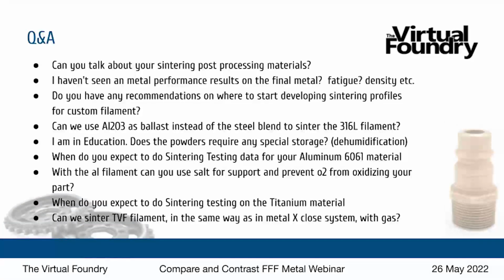Brad, can somebody use regular Al2O3 as a ballast for sintering 316L filament? They're fresh out of steel blend. Right.